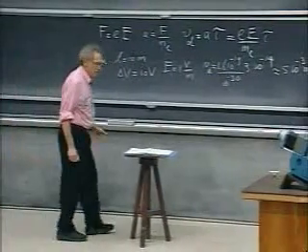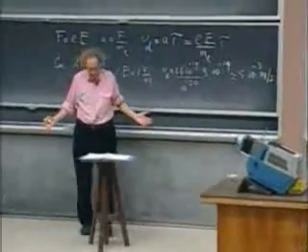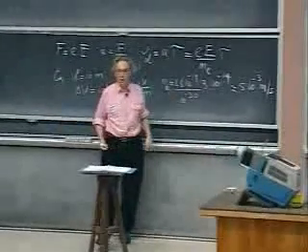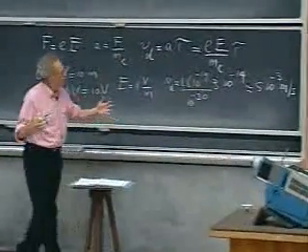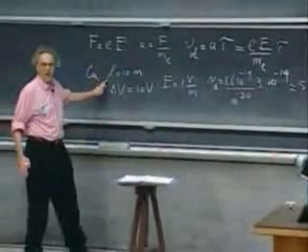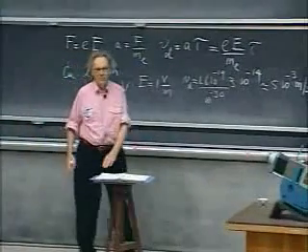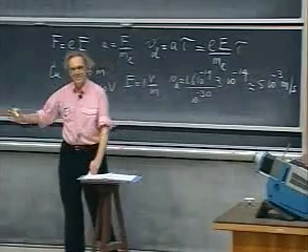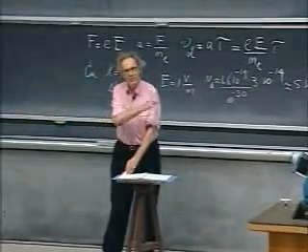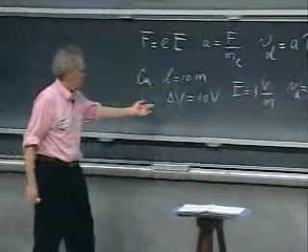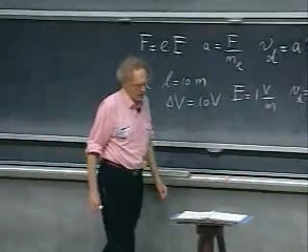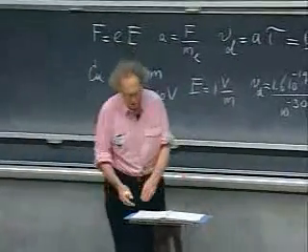And this goes very much against your and my own intuition, but this is the way it is. I mean, a turtle would go faster than these electrons. To go along a 10-meter wire would take half an hour. Something that you never thought of. It would take half an hour for these electrons to go along the wire if you apply a potential difference of 10 volts, copper 10 meters long.